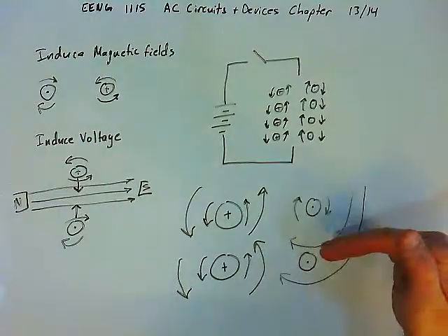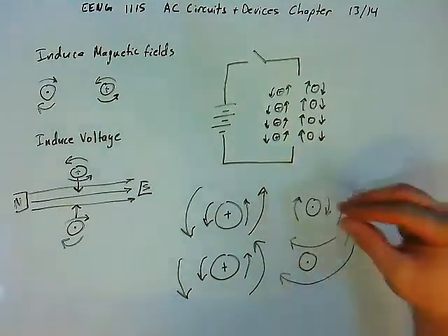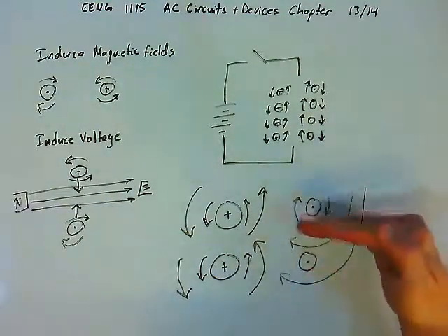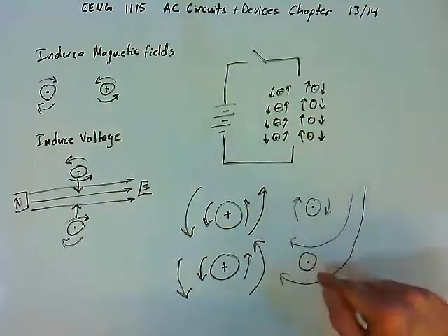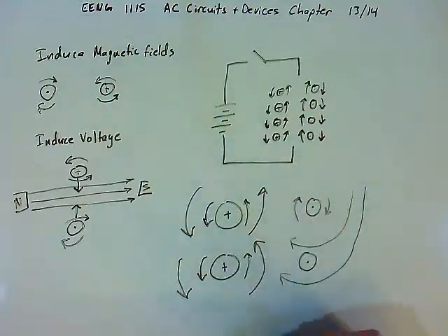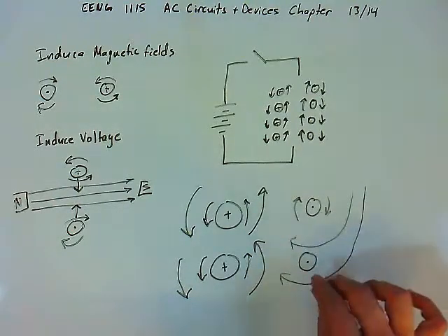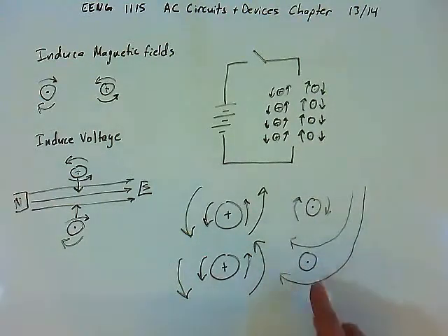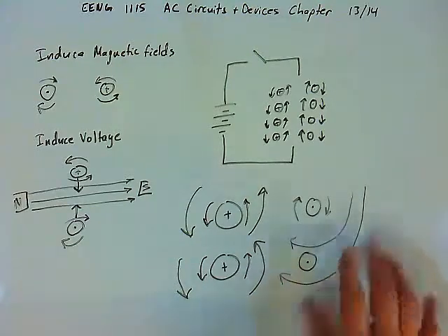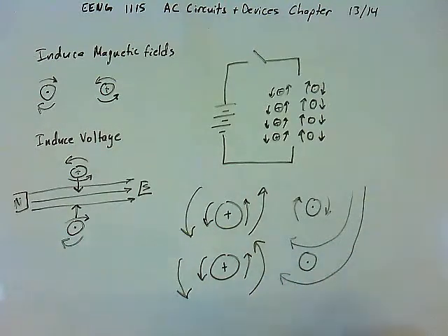As these magnetic fields were growing, because they expand, they cut across the conductor. And as those flux lines cut across the inductor, we saw that they induced voltages in the opposite direction that they were actually flowing, and that slowed the current down. Rather, it prevented the current from increasing to its maximum value instantaneously.